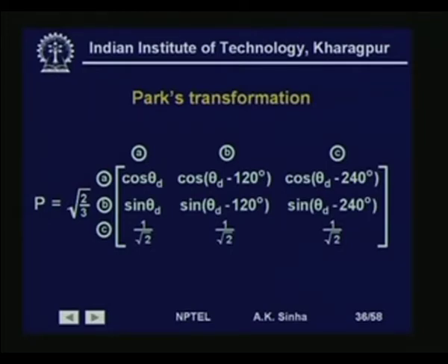Since that has nothing much to do, we generally do not use that part, but we have the D axis, which we call the direct axis, which is in phase with the rotor, a quadrature axis which is at 90° to the rotor, and the third one, a 0 axis. So, the DQ0 frame of reference.